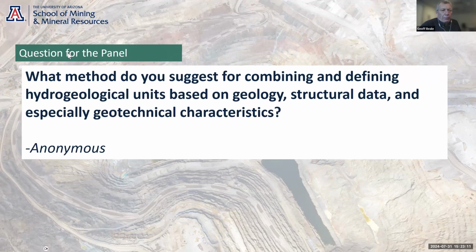The wider hydrogeology is typically based on piezometers, water levels, and responses. At the slope scale, that's when the geotechnical characteristics come in, and probably the key one would be fracture frequency, fracture orientation, and evaluation of the local scale structures, local scale joints and fractures.